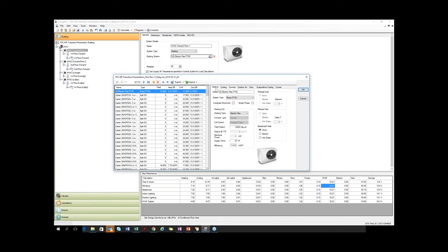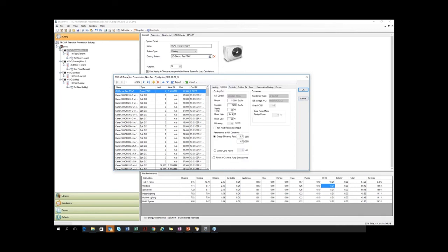Second thing is heating and cooling outputs. In EnergyPro 5 residential, you could input 1 or you could input like 1,000,000 and it wouldn't make a difference. It would auto size the load for you. EnergyPro 7, it's not the case. So you need to be sure you're inputting, if you don't have the exact value, a reasonable estimate. Next item here is the fans.